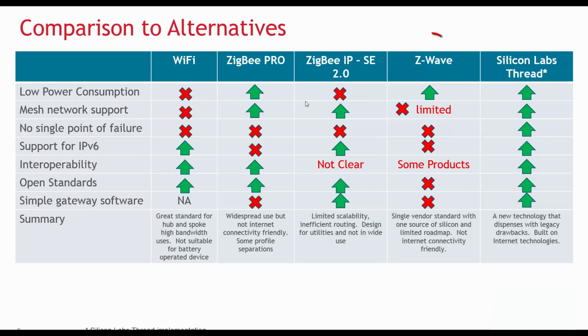Next we have Z-Wave, a proprietary sub-gigahertz home control standard designed and controlled by Sigma Designs. Although lacking the large-scale mesh networking capability of its ZigBee counterparts, Z-Wave often achieves wide coverage of the HAN via increased propagation of signals in the 915 MHz band, and its low power consumption and established vendor ecosystem have made it successful in the North American market, especially in the years preceding wide adoption of the ZigBee home automation standard by many device vendors and MSOs, major service operators.